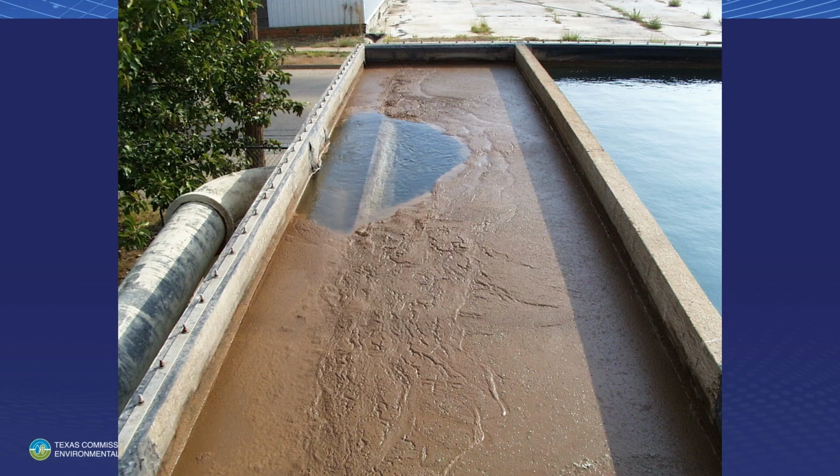How many of you have seen that at your water treatment plant? How many of you have figured out why it happens? How many of you use sprinklers to knock it down so that it'll settle out? In West Texas, now I don't know about East Texas, I'm a West Texas water treater. My mentor, Mr. Holbert, told me that I could treat water by whipping it with a stick. And that means that my water's pretty stable. I got a lot of alkalinity in it, and I can do just about anything in the world to it and not screw it up.